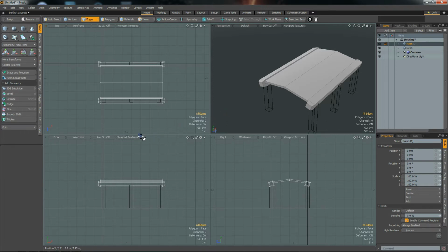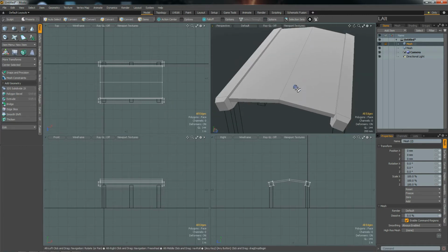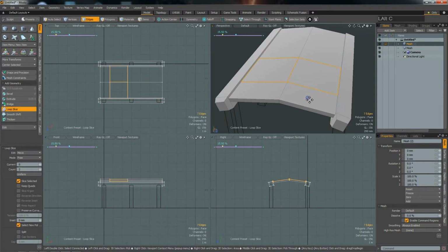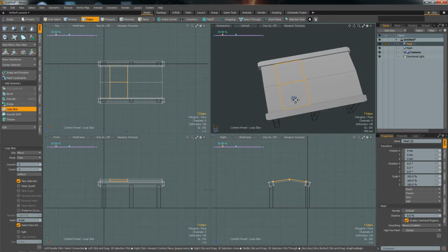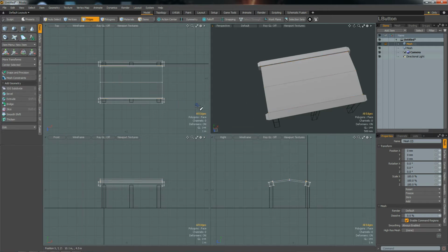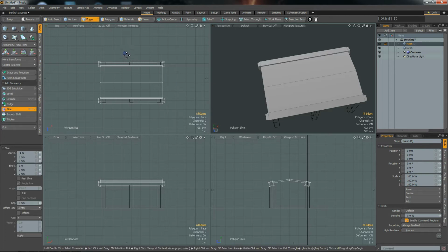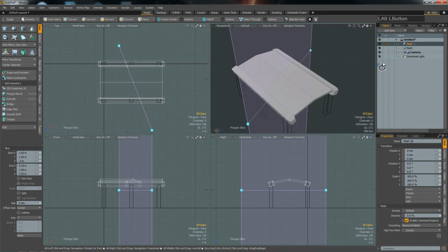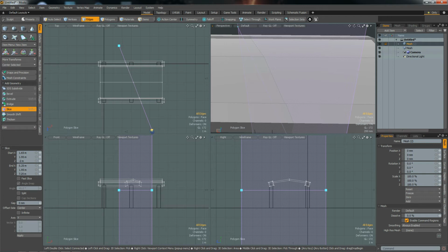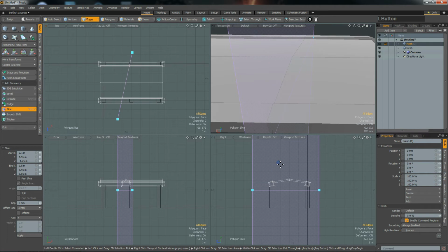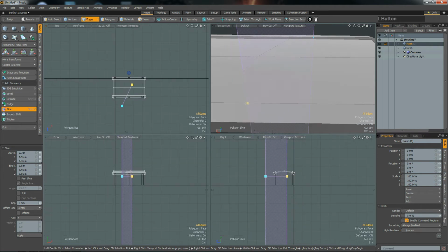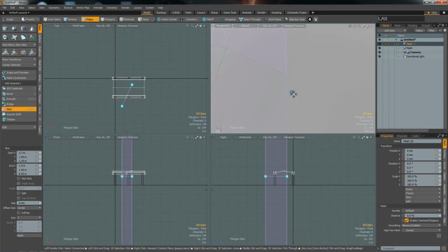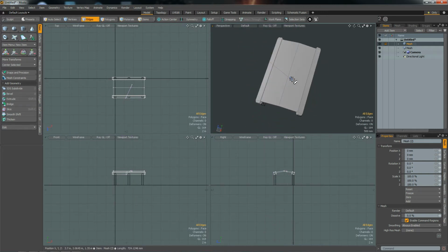If we want to cut into things, not the way I did it before, where I selected 2 or more edges and hit Alt-C, which gave me this edge cutter, I could, independent of any selections, hit Shift-C, and then I can draw a slicing plane into the world and move that around. This slicing plane is actually just the plane that is visible. So if it's not going completely through an object, it's not infinitely extended beyond that. Here you see that the edge created by the slicing plane just stops where the plane stops. So you can also partially slice an object if that should be useful in your case.